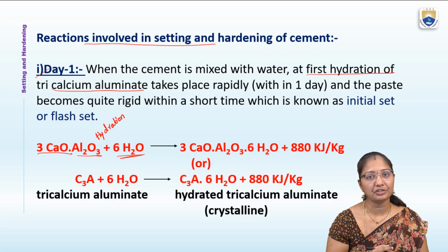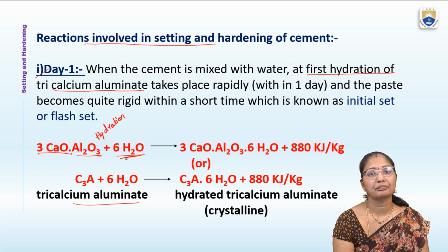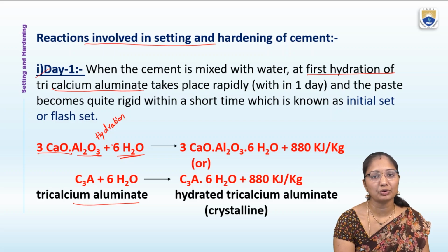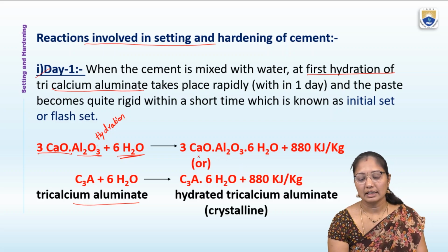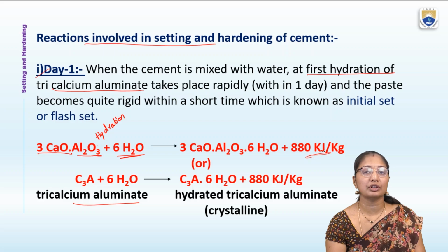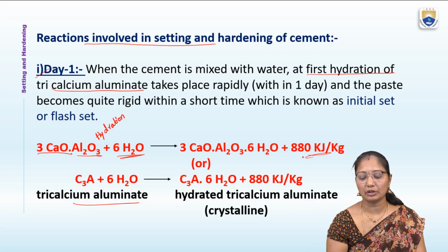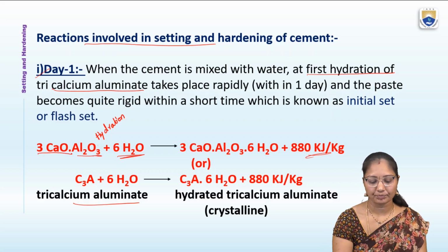Here the tricalcium aluminate reacts with the water molecules, giving hydrated tricalcium aluminate. It is an exothermic reaction which gives energy. Here 880 kilojoules per kg of energy is released, which means it produces heat.